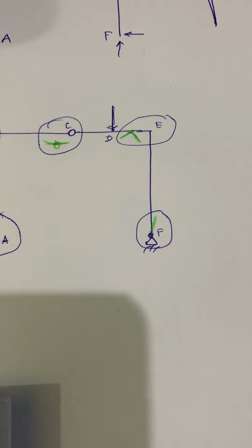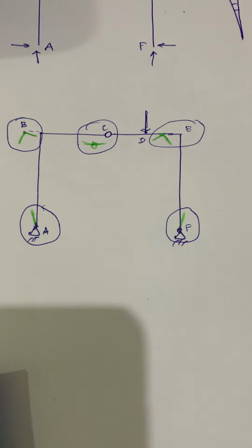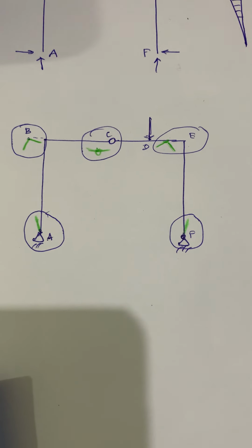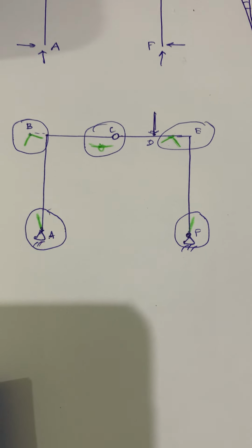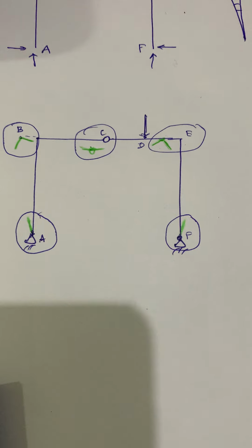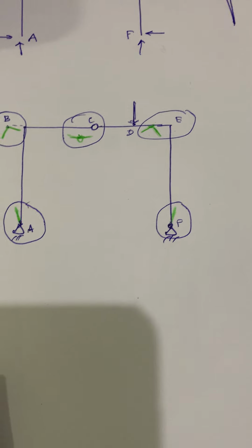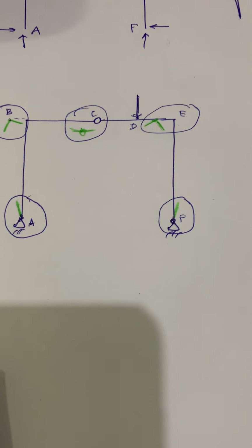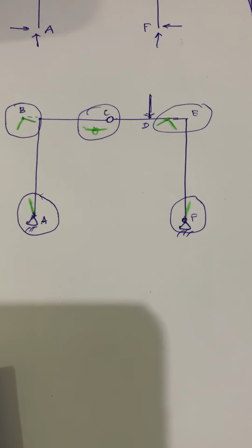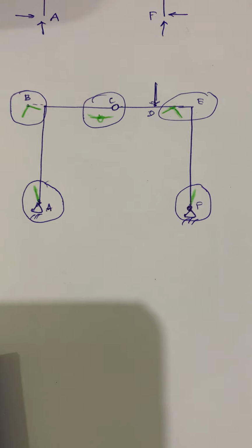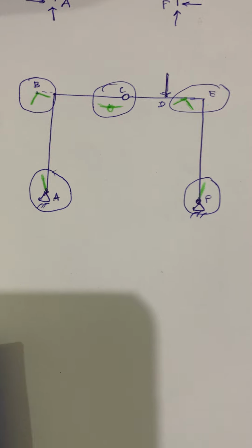Now we note that support points A and F are restrained both horizontally and vertically. As they are hinged, the slopes of the members may change at these points. The corners at B and E may rotate and move horizontally but may not deflect vertically. Also, we observe that the hinge C may deflect vertically, but it will have the same horizontal displacement as that of B and E due to the assumed axial rigidity of the horizontal member BCD. However, members connected at the hinge can take different slopes on either side.